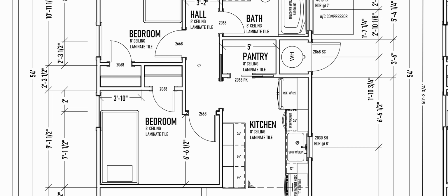Let's see. So I could definitely put one here and maybe put one here. There is a rule for the minimum angle I have on my lead brace. I can't put it too steep in my wall; it won't count. I'd have to check to make sure that I can do that. This one's great, but I'm not connecting all the way through the house here, so it's not ideal.